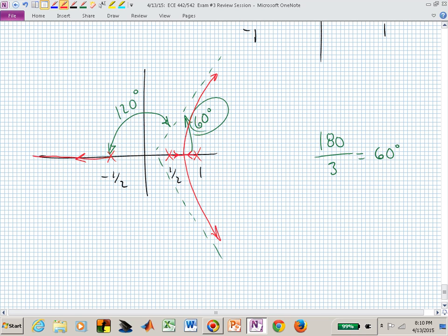And these root locus diagrams look pretty clean. They don't go real weird with how they are sketched. These are fairly smooth curves. Why? Because their angles are minus 180 all the time. But is this system ever stable? How many think yes? Give me a hand. No, not that kind of a hand. A raised hand. So yes, it is stable, isn't it, initially?